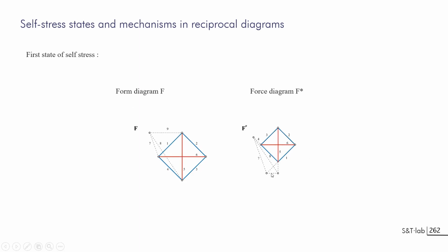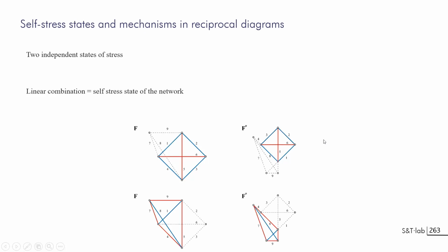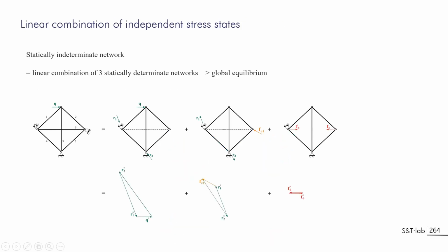And we'll have on the complete force diagram the components linked to these forces. So you will need another combination, self-stress as two compressed bars here. And this time you have a closed cycle of forces in tension to equilibrate them. And you will have the corresponding force polygon. So this is self-stress 1, self-stress 2, and you have stress also occurring from the system with the applied forces. So you can see you have several supports with different directions and one force that will be applied here, and you will be composing all this system when retrieving this force.